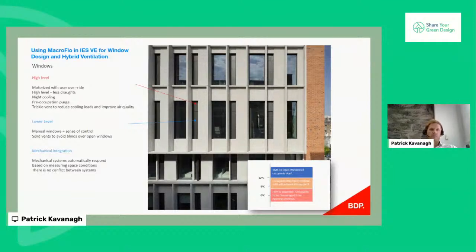The reason for this is that research we've done on previous office projects found that, while you provide openable, naturally ventilated spaces, depending on their orientation and even just by occupant use, people were closing the blinds when the sun came out and not reopening them, and this was impacting the natural ventilation strategy. So by doing this, a user could adjust the blind height as required, but it wouldn't affect the natural ventilation strategy.